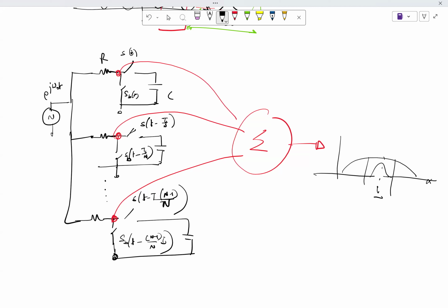When I say distortion, I do not mean nonlinearity, but without anything else available. So in this case, if you do not have these 4 of them together, you have only one of them, and you observe the voltage only across the switch of one kernel, you are going to see tones at omega s, where you want, but you are also going to see tones at 2 omega s, 3 omega s.